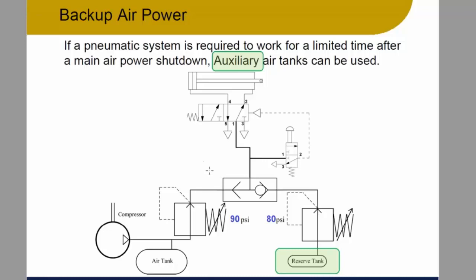You already are thinking ANDs or ORs. You're thinking control systems. And we know from the first 2 or 3 labs that you can design a purely pneumatic control system just with air. No relays, nothing. And you can put some degree of logic in there, kind of like if cylinder A extends, then cylinder B should extend. But in this case, you can use this as an OR.